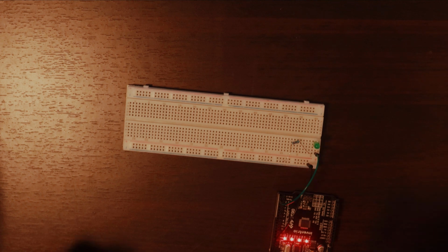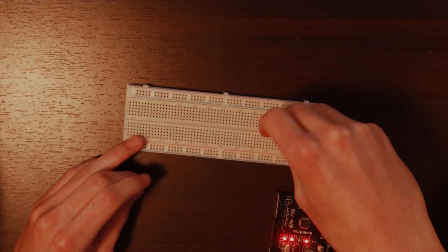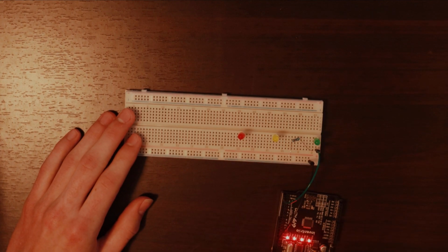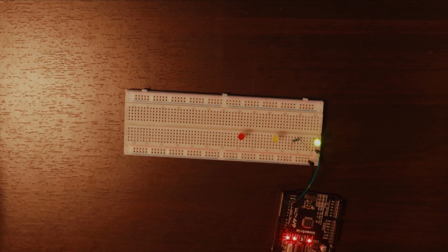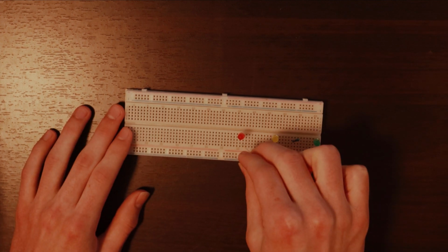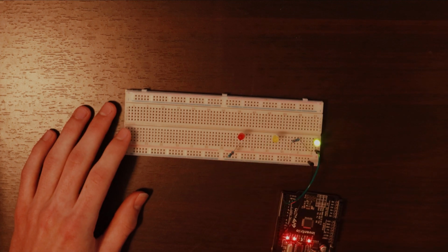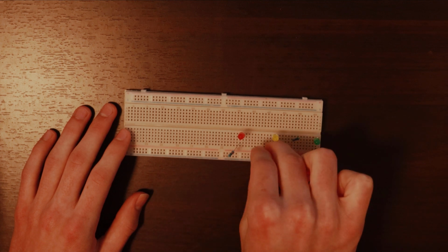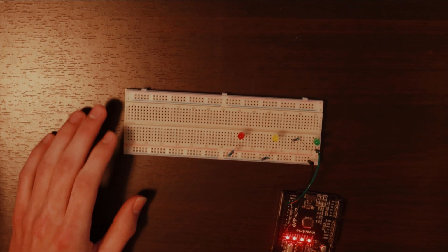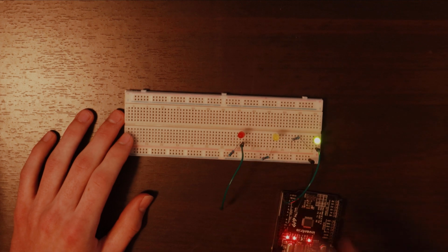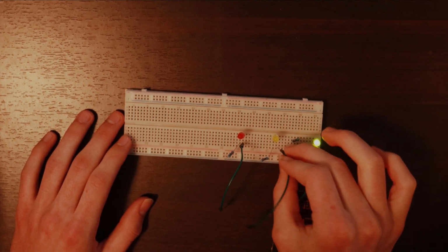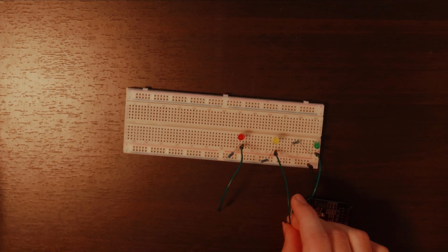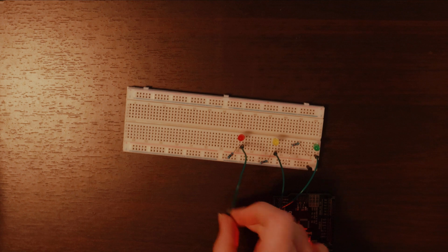Let's add our LEDs. Here I'm adding a yellow one and a red one, like a stoplight. I'm making sure all of the longer leads on the LEDs are to the right, so that we know which side to connect the positive and negative to. Next, I'll add a resistor from the negative side of each LED to the blue line here. And lastly, I'll add a wire coming from the positive side of each of these LEDs and going to a port on our Arduino. I'll connect the yellow one to port 1 and the red one to port 2.